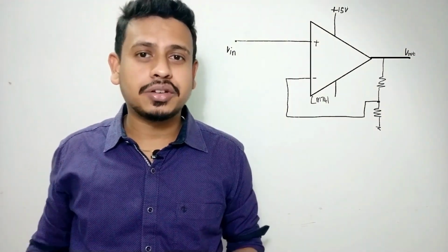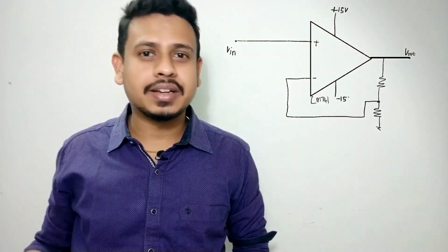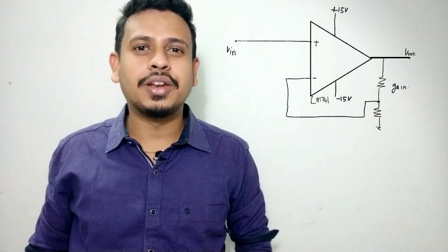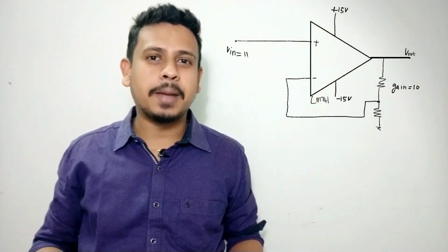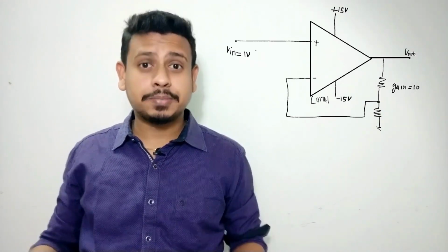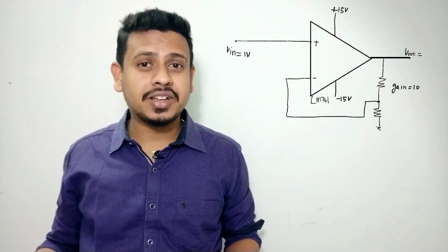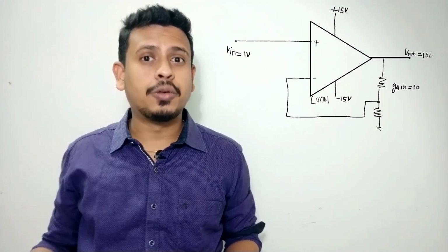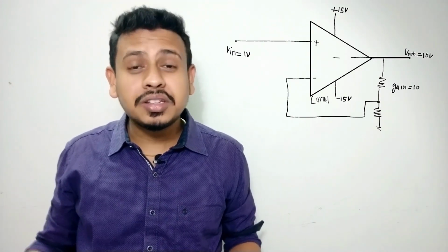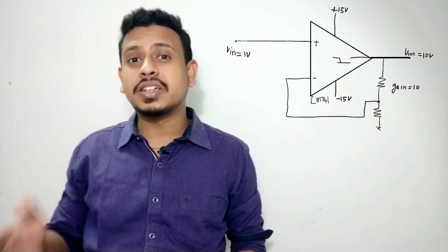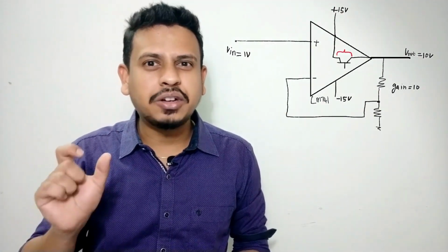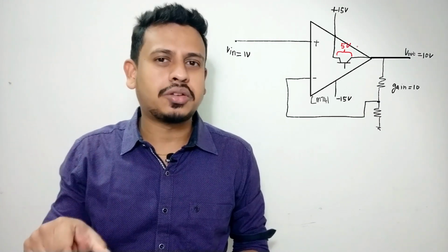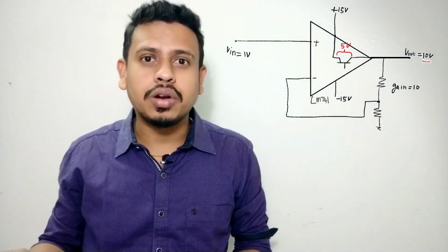Let us consider an op-amp based non-inverting amplifier circuit of gain 10 connected to a power supply of plus 15 volts and minus 15 volts. Let us assume the voltage at the input of the amplifier is plus 1 volt. The expected output voltage would be 10 times 1 volt, which is 10 volt. Where does this 10 volt come from? The output section of the amplifier takes the 15 volt power supply, drops 5 volts within its own circuitry and gives out 10 volt on its output pins.